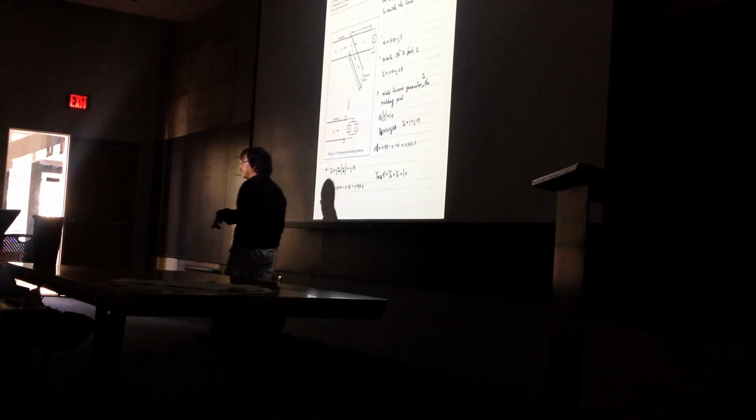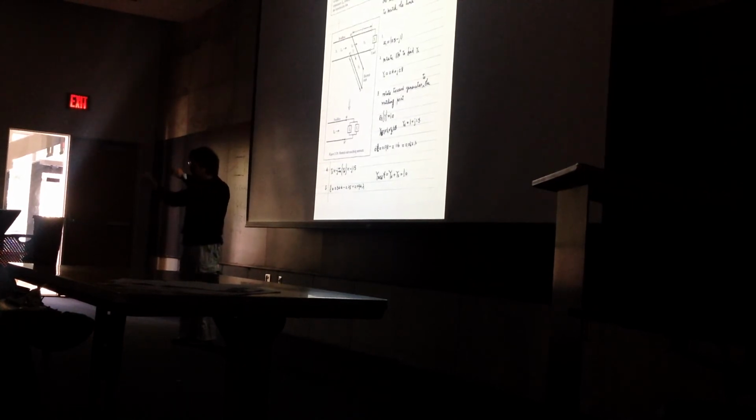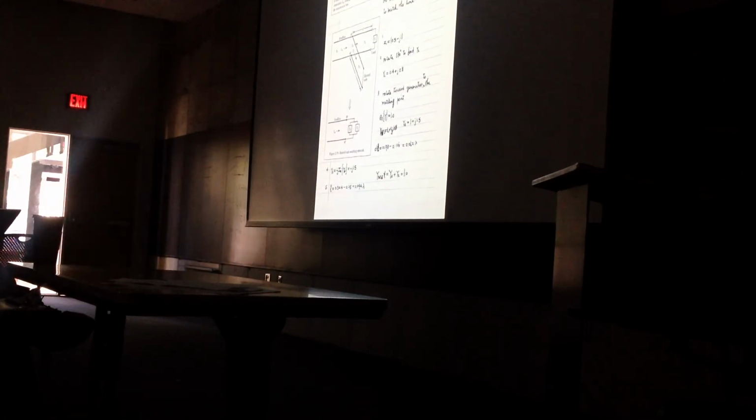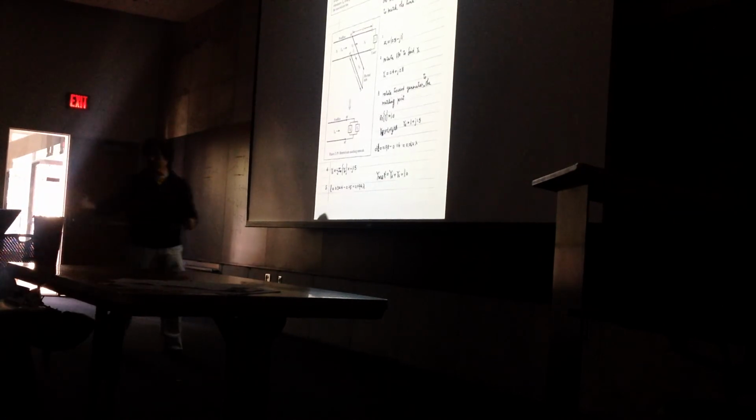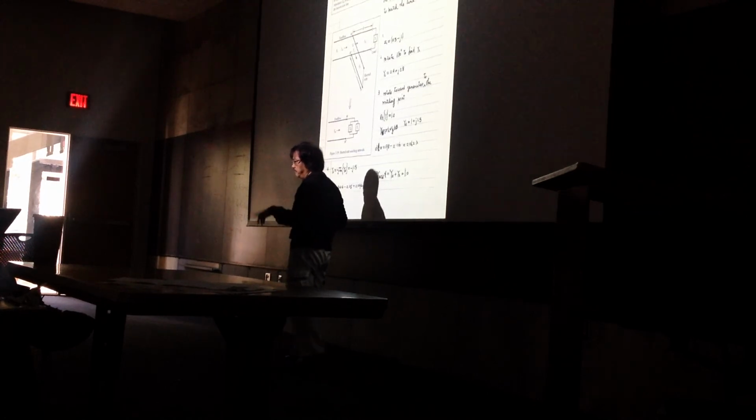Where did you get the 0.25 from? Look at your Smith chart. That's the difference. Here it tells you it's 0.25. Look at this number here. Okay, 0.25. So it goes from here to the outside. You actually intersect your Smith chart on the outside, and then the number tells you what the reference is. You intersect that, and the other side will tell you it's 0.344. That's where I got the number.